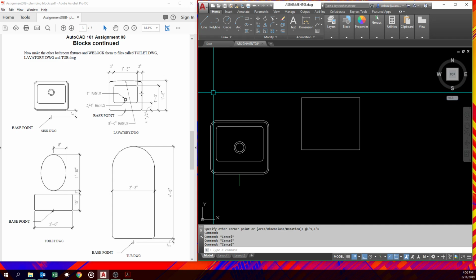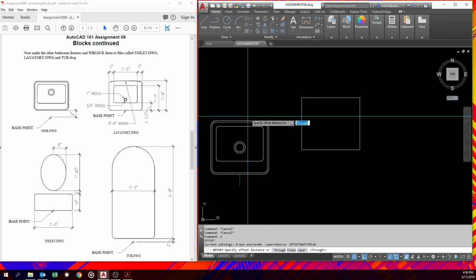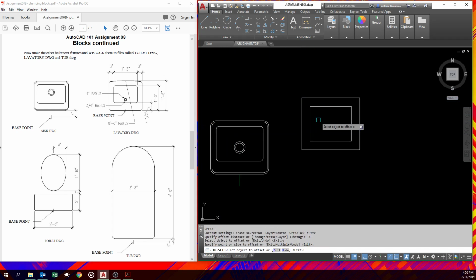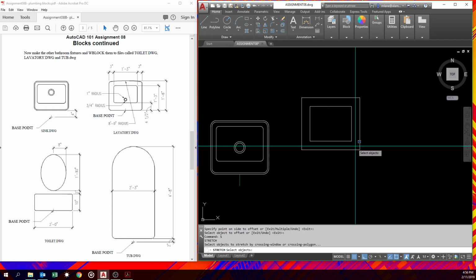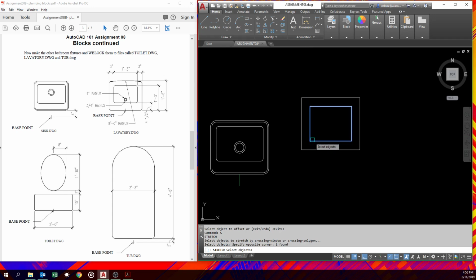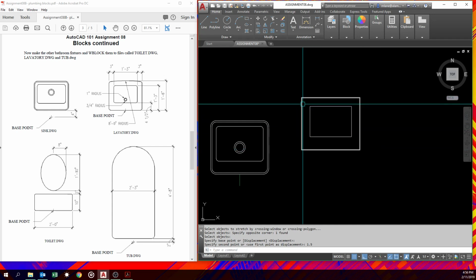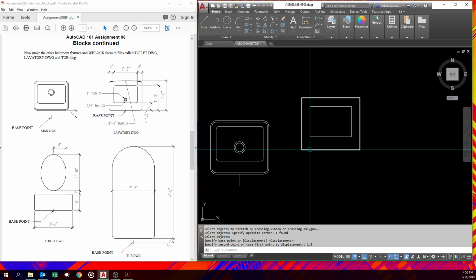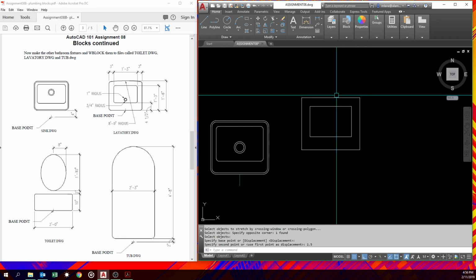You'll notice we've got 3-inch offsets, a 4.5-inch offset here, but these three are off. So we can do the same thing like we did here. Offset 3. We'll have to stretch this up. It's 4.5 inches. So stretch. Remember, stretch has to be with a crossing window. We need to go up 1.5 inches. Make sure your ortho's on. All right. Now we can start putting in some radiuses that look about right. Don't put the radius here because we're going to come and replace this line in a minute.